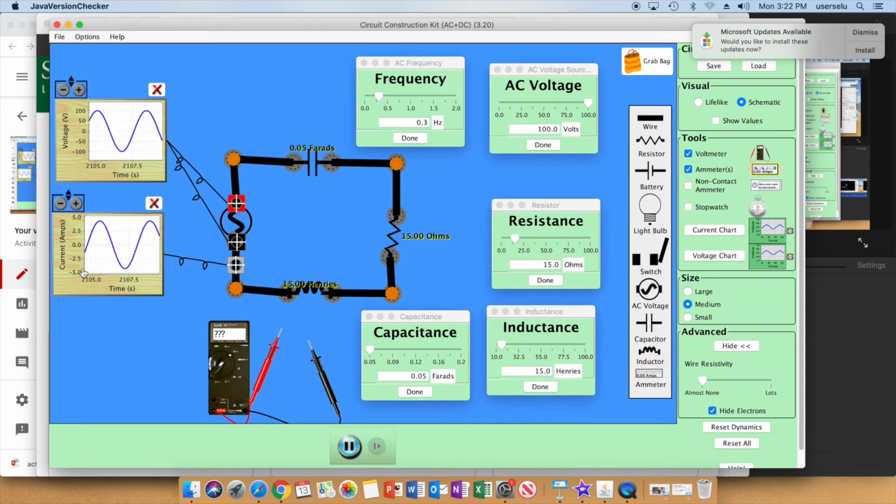So what you should be able to do is to calculate the Z of the RLC circuit, using the recipe on the slides, and see how it compares to the Imax and Imin that we're seeing if you calculate using that impedance divided into the voltage.